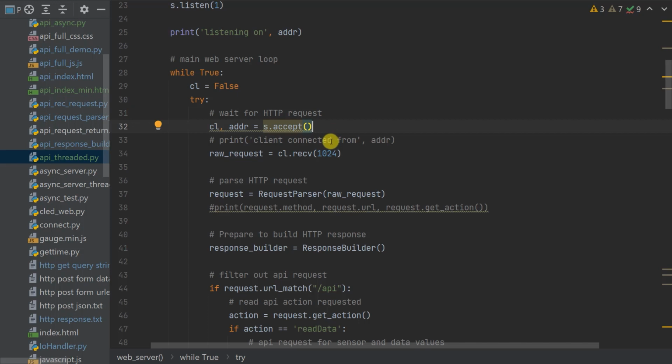And on these little microcontroller boards, we really do want to make the most of the power that we have. So we know that if we have a single core, we can still utilize that fully by using asynchronous programming. So I guess the ultimate then for our Raspberry Pi Pico is to combine both our multi-threaded coding, so that we then use two cores, with our asynchronous coding, so that the core that is handling our web server can actually get on with other tasks while it's waiting for the next HTTP request. So let's have a look at how we can combine both of these techniques to make full use then of our two cores in our Raspberry Pi Pico. And of course this will be identical then to running it on something like the ESP32 with the two cores.